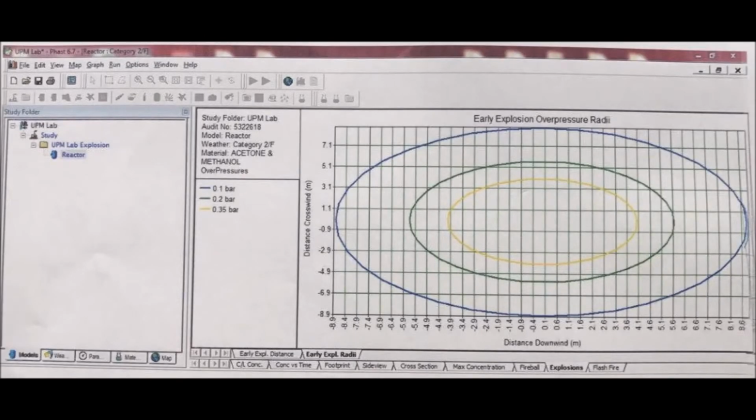This explosion contour explains a 2D explosion result. It is in a circle shape because the readings produced by FAST are in diameter. The innermost contour represents the strongest explosion, which can cause immediate fatality if a person is in that zone.